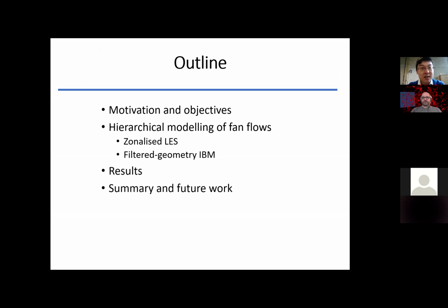First, I give a bit of information on why we want to do this work. The second is to introduce our methods, mainly on modeling the fan stage flow. There are basically 2 parts. One is the Zonalised LES method, and the second is how to blend the mesh resolved geometry and the low order IBM methods. And finally, I give some results of the simulation and compare them with the experiment to validate our results, and then give a brief summary and outlook on future work.